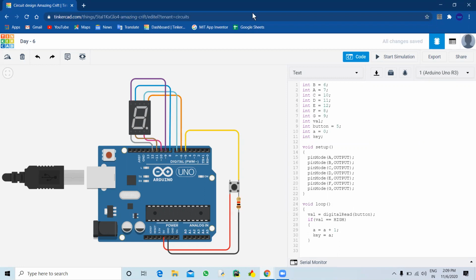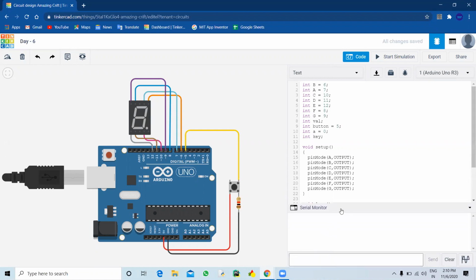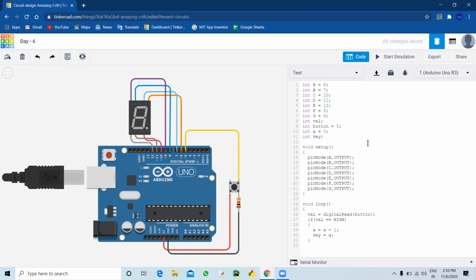Now we will come to the switch cases. And one more thing I would like to tell you, this 7 segment might not work fine. There is an error that I will tell you in just a second. So we will only bother about the printing of values. For printing, we will just start the serial monitor. So I will write Serial.begin, then I will write 9600.